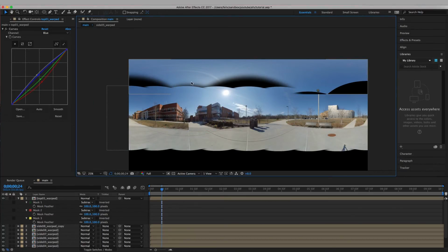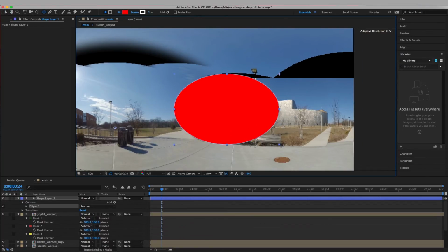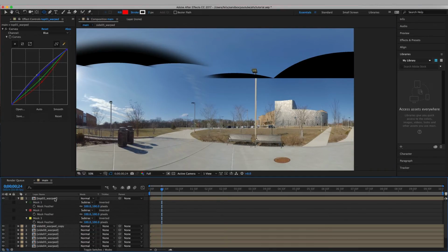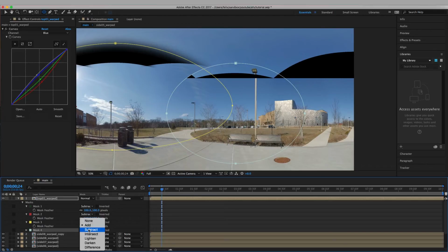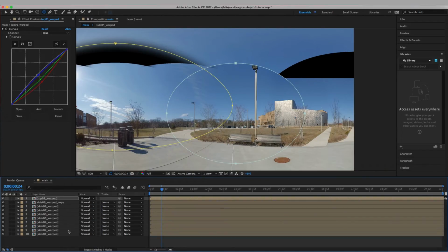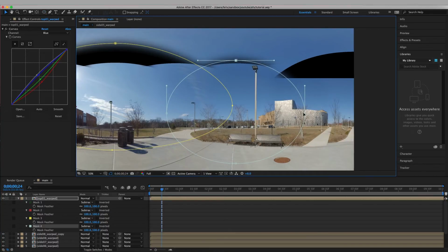So if you look, we're getting a faded edge going on over here. So here we're going to draw a circle first, and then I'm going to select it and delete it. Then we're going to make sure that top warp is selected, and start drawing our mask again. Same thing: select this to subtract, press F a few times to set the feathering rate, and then we just push this up.